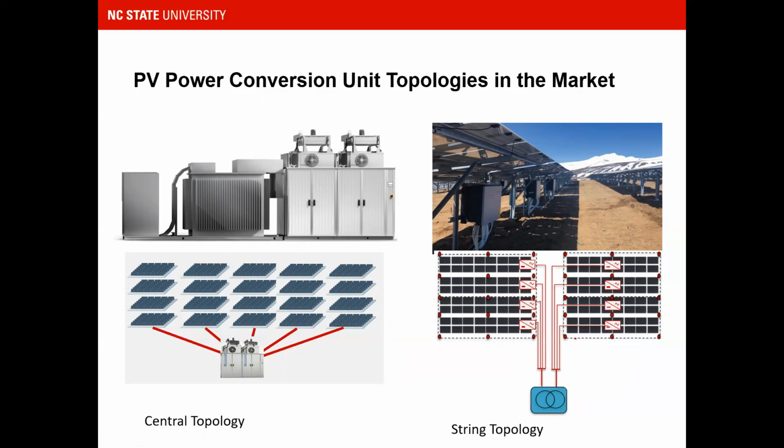It needs higher technical expertise for maintenance and installation. Also, you see we have a lot of modules that can be far away from the inverter, so we require long cables. Long cables mean a higher installation cost for the cable, and also losses. We increase the losses when we increase the length of the cables.